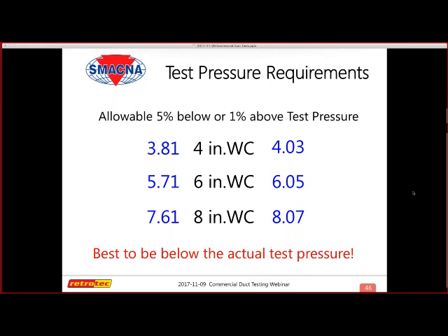You don't need more fans just to confirm that you're failing. More fans will not help you pass. They will just allow you to get to a higher pressure. Again, you still failed. So the gauge, I'm going to go through that as to why the gauge can tell you with almost any kind of pressure that you get and how leaky it is. The end could almost be off on one of your ducts, and I can obviously tell you're failing.